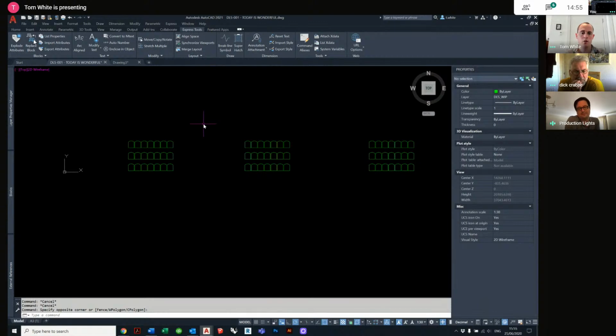Block replace does work. And there's a really powerful tool in Design Center, which I have to talk about at a different time, but it's how you update a block from a different drawing. I find I use it all the time. Yeah, a Design Center somewhere had open continuously. It saves so much time.